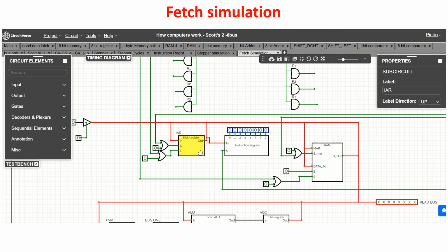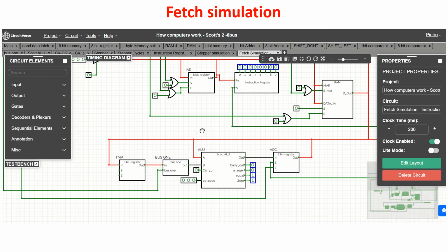So we have to think that the content of the instruction address register is on the bus, and we want to update this. So we give a bus 1 pulse, so in the input B of the ALU there is the number 1, and in the input A of the ALU there is the content of the instruction address register. Because the opcode is 000, we don't give any signal or pulse to the opcode, so we don't change the opcode, which stays at 000. So with this opcode we perform an addition.